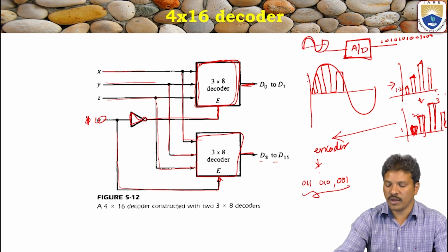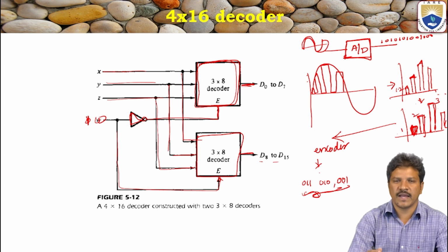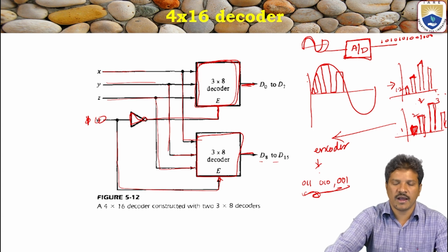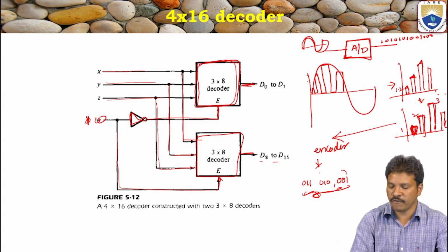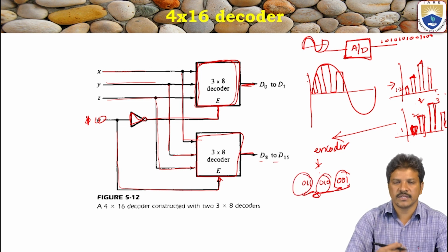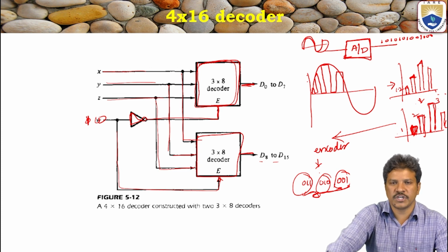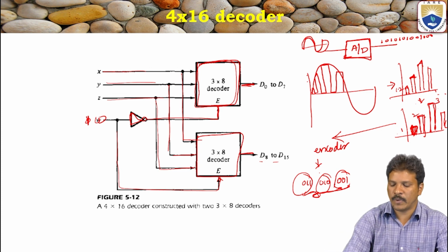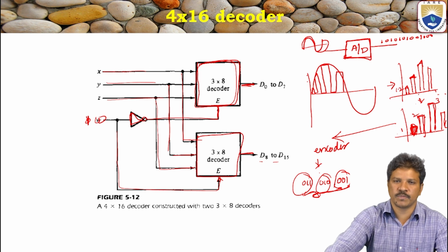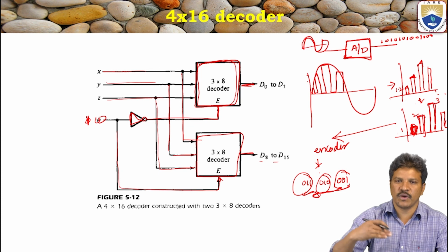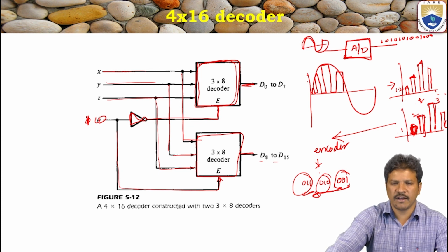The input signal is analog. We generate the binary information that can be transmitted by the channel, and at the receiver we receive this kind of packet of 3-bit inputs. Serially, then by connecting the 3 inputs, they are converted to decimal numbers of samples. Those decimal number samples pass through the low pass filter, and then generate the continuous waveform of the analog signal.